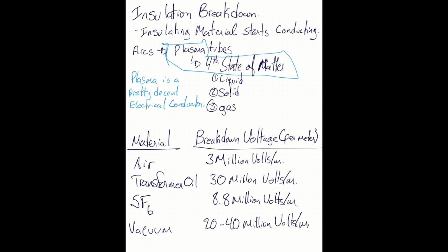So this is a table that we're going to be referring to often, and what sort of insulation we're dealing with determines what sort of spacing we need on our things to make sure we don't hit a breakdown state where we'd establish an arc, because at those distribution voltages, you've got enough energy that you can deliver.